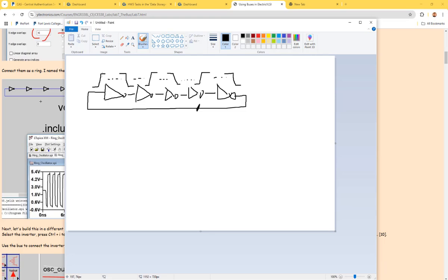How could you have 2 different signals? Isn't this the same wire? It's always the same wire, right? And we are assuming this one goes from 0 to 1, and on the other side of the wire it goes from 1 to 0. How could that happen? It's all because of the time delay in the middle.